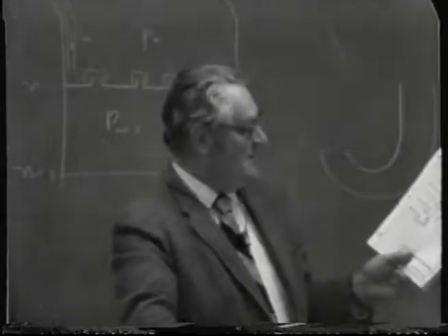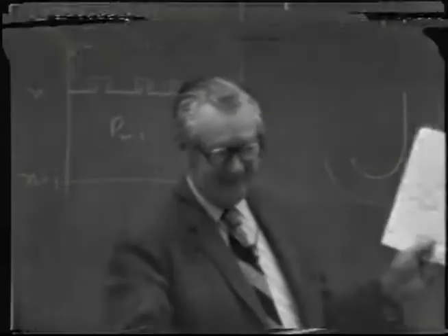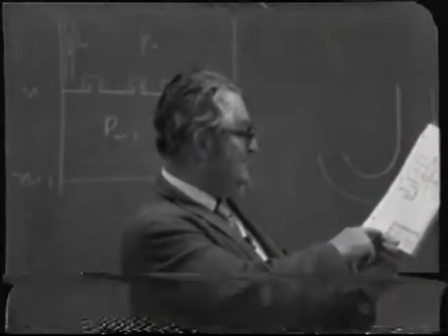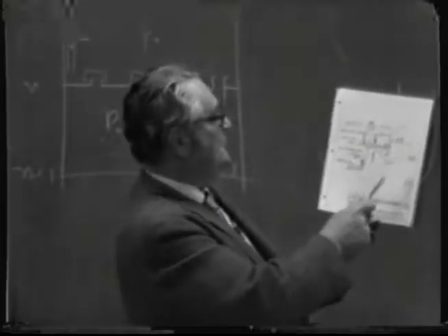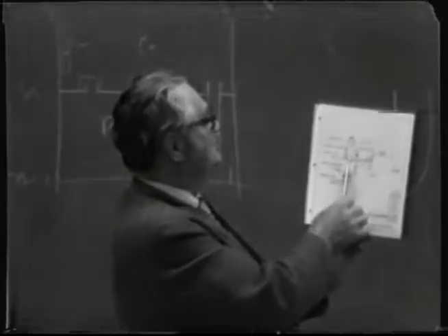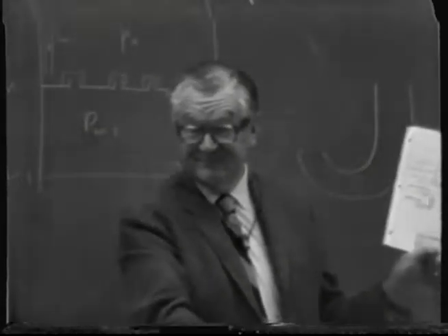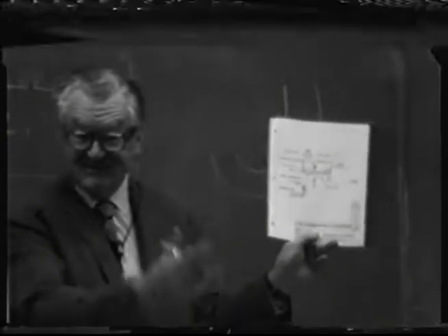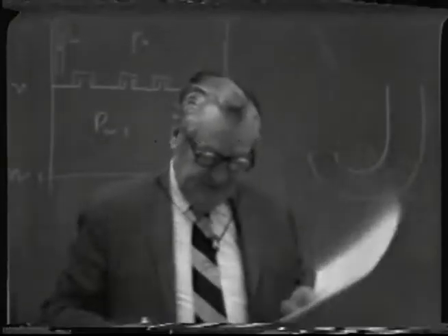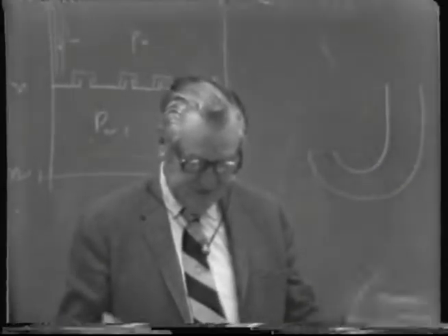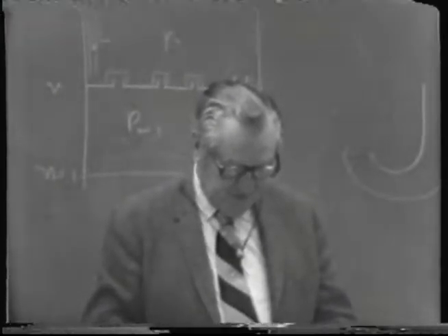Initially, when I got a copy of this, I couldn't understand how this worked very well, but I talked to Mr. Nallum, who's a designer who drew this drawing not too long ago, and he pointed out that they didn't show in the drawing this tube that rises up to the top of that separator chamber, because it's inside. So I've shown here the dotted line. That's where the vapor escapes from the liquid and mixes with the steam. And this is the principle called vapor recompression.